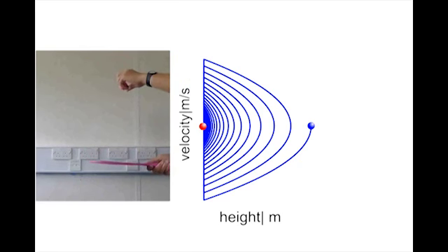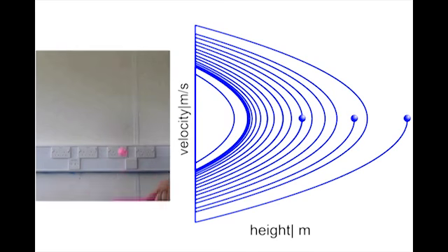We can represent the ball example on the phase plot of height against velocity. By coupling this system with a neural oscillator, the motion becomes periodic and eventually converges to a repetitive motion called the limit cycle, here shown in red. This process demonstrates our global motor controller.